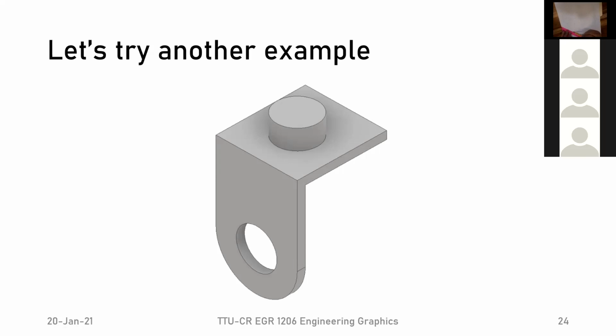To do that, I first draw myself the diagonal. And again, this has to be nice and soft. It might be a little thicker than it should be, just so you're able to see it. You can see this diagonal line that I just drew? Yes. Okay, good. Right, so we know this would be the entire diagonal. We said we need to have half of that. Half of that diagonal is here, and then the remaining part is this, and we want half of that again, so that would be here. So that would be another point. I'll go ahead and start erasing some of these so I don't get confused once I start drawing my circle.